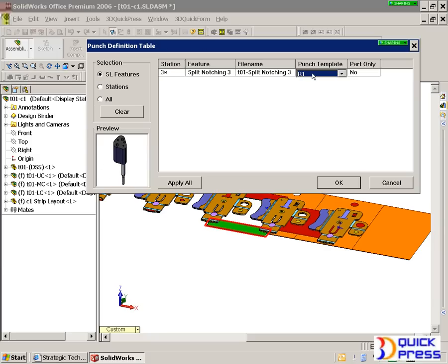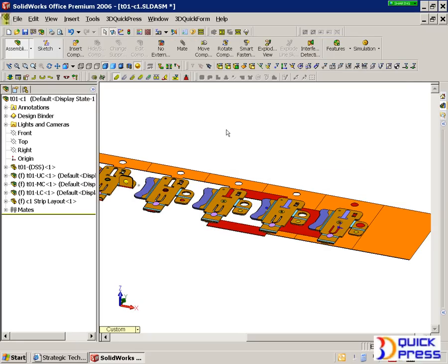So you can have everything from a manufactured, like a ball lock punch. You may want to do some other type of configuration where you have a fastener through the bottom, step with shoulder, pedestal with multiple fasteners, dowel pins, and so on. The main idea here is you can tailor it. Also, the openings that go below the die steel, you may want them to all be direct offsets. You may not. You may want them to be all rectangular. These are all variations of this.